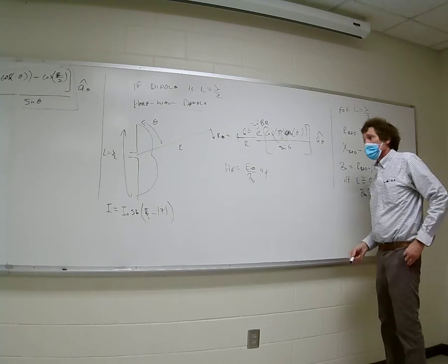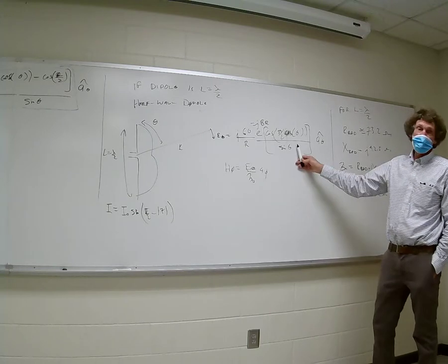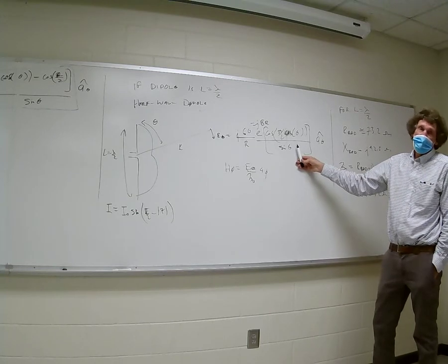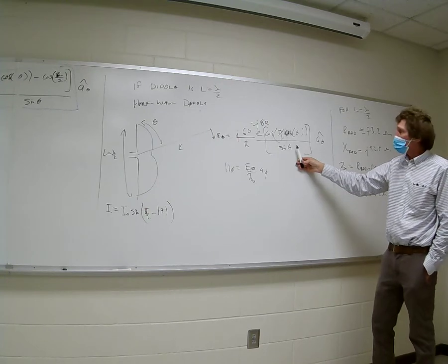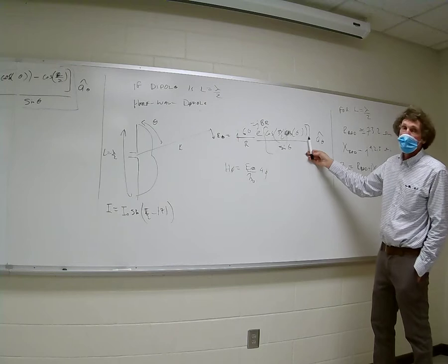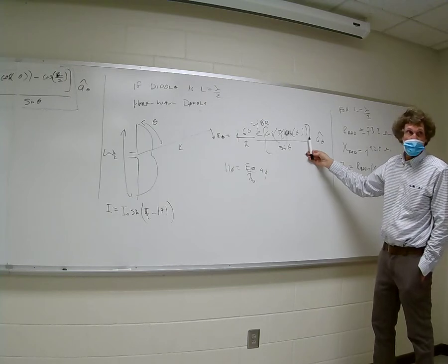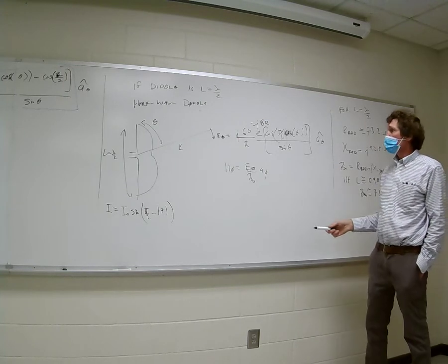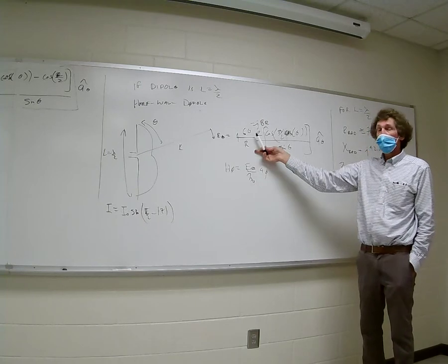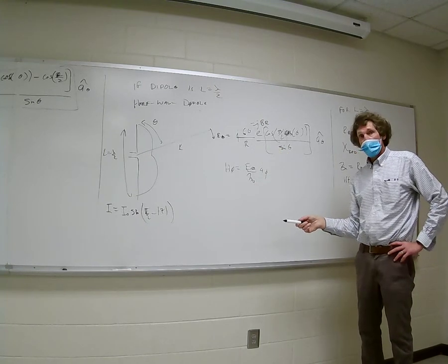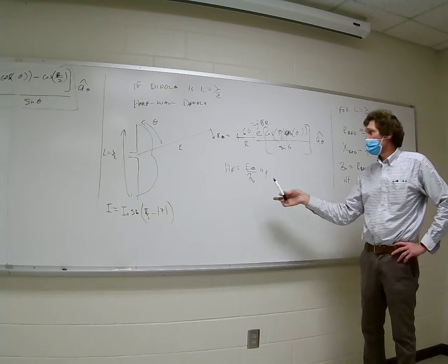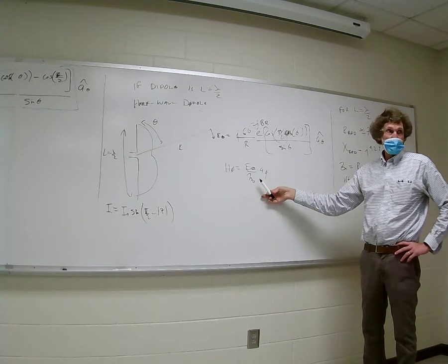Now, if you have that, a good question is how do you get the power? Well, you could take 1/2 the real part of E cross H conjugate, right? We'd find out that this angular form here would square itself, wouldn't it, class? We'd also find E would be 60 squared, and then it would be divided by eta, which is 120 pi, right?